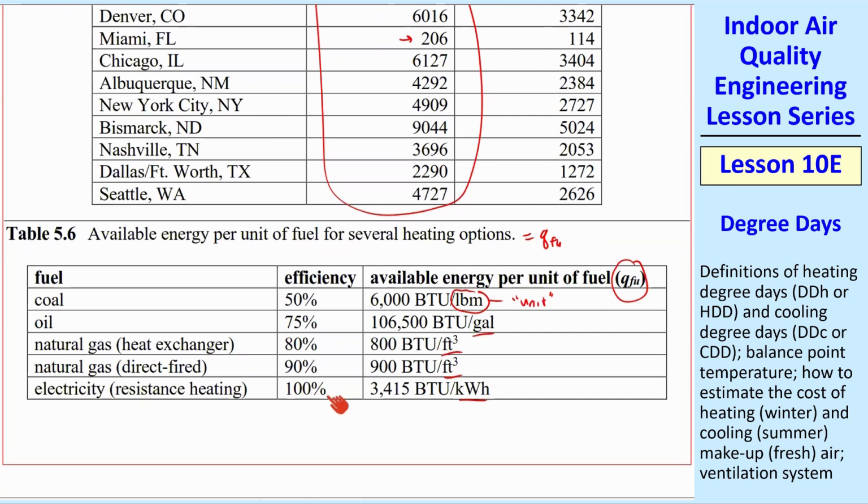And now let me just also add here, since these are much more popular these days, a heat pump with a coefficient of performance of 2.0, let's say. The efficiency is actually 200%. For each kilowatt hour that you spend in electricity, you get 2 kilowatt hours of heat. This gives you 6,830. There's a factor of 2.